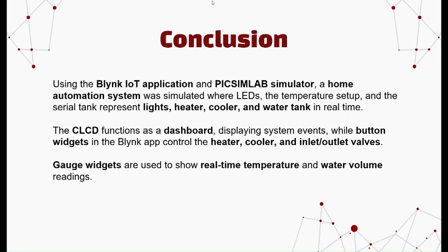And by the way, the conclusion is: using the Blynk IoT application and PICSimLab simulator, a home automation system was simulated where LEDs, the temperature setup, and the virtual tank represent lights, heater, cooler, and water tank in real time. The LCD functions as a dashboard, displaying system events, while button widgets in the Blynk app control the heater, cooler, and inlet-outlet valves. Gauge widgets are used to show real-time temperature and water volume readings.